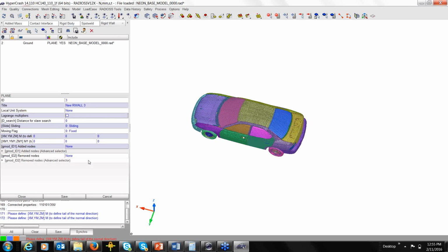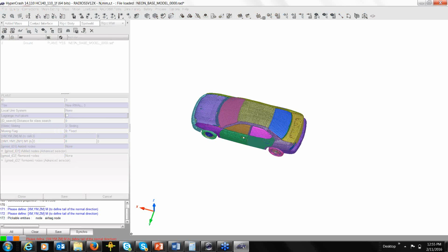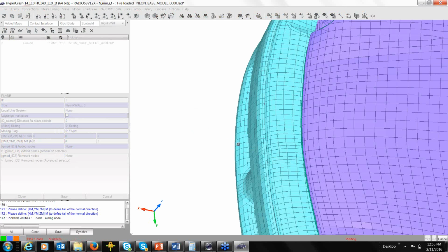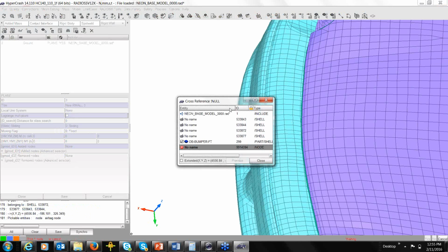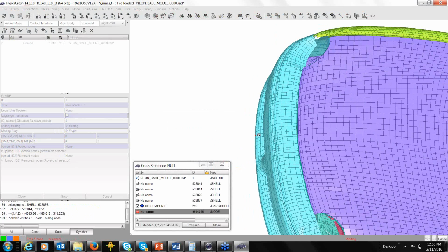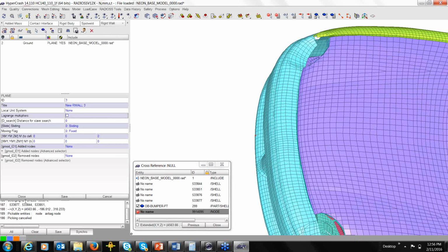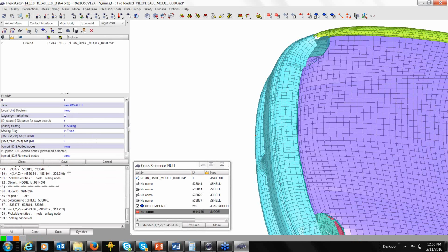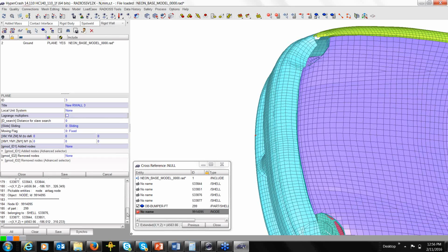So it gives me this window, and it asks me, okay, I need to create my node. First, before I do that, I need to know where I can locate my wall here. I know I'm going to locate the wall somewhere around here. So I want to find the further node information, so that when I create my wall, I can identify where exactly my wall is. So down here, I just select a node to see the information of that node.